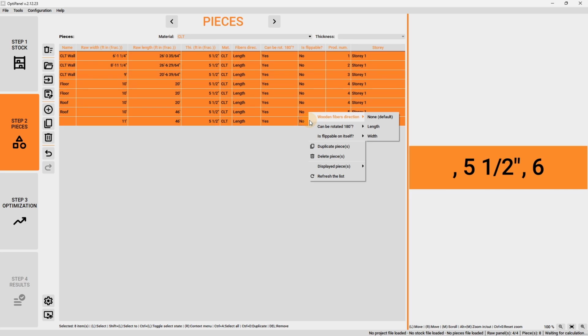They are taken from a panel that is perfectly symmetrical. So the top face and bottom face are made of the same material with the same lamellar orientation and the same finish. If that were not the case, you would leave that as not flippable, meaning that the elements will always be placed with the same orientation as they have in 3D. So all the elements will have the thickness oriented in the same direction in the nesting volume.